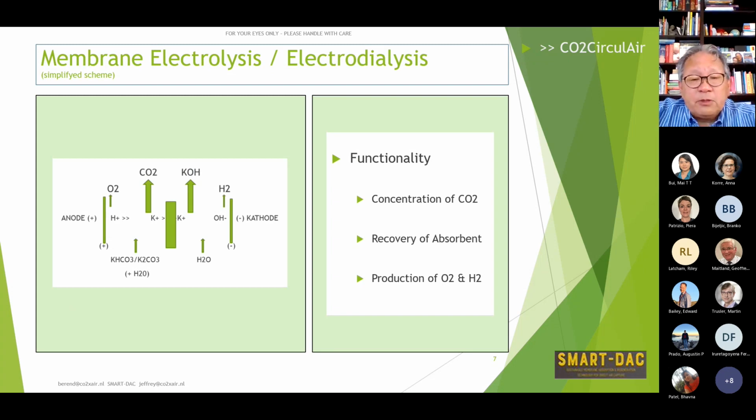The second step, the concentration of the CO2, is done electrochemically with membrane electrolysis or electrodialysis, where, depending on how we use the process, we could even also produce oxygen and hydrogen. But at present, in the project we're working on, we suppress the production of O2 and H2.